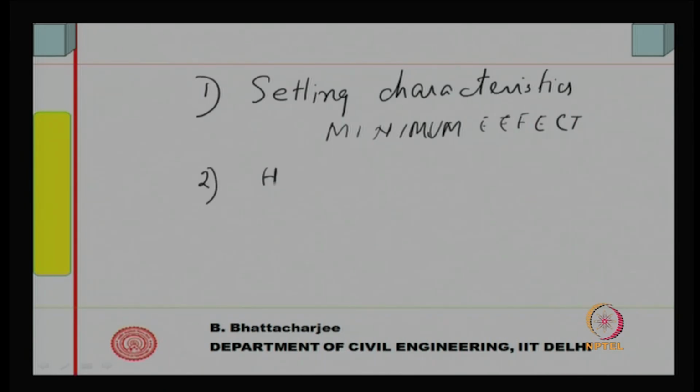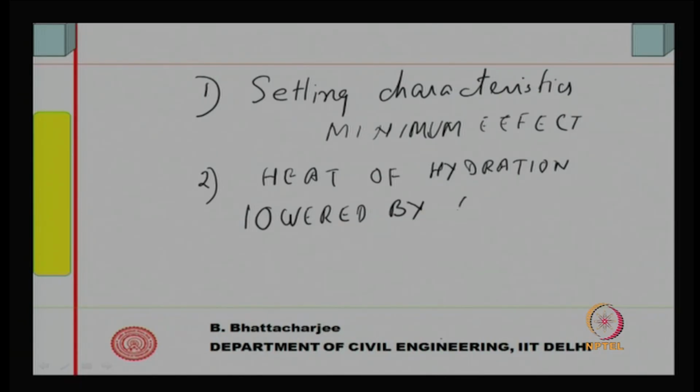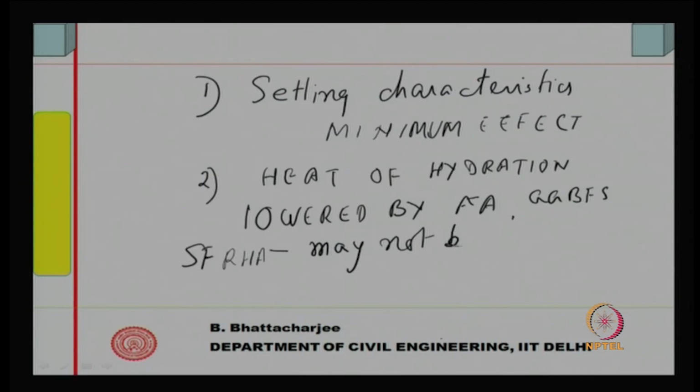Heat of hydration is lowered by fly ash and GGBFS, but silica fume, SF, and RHA may not be as effective as fly ash and GGBFS.